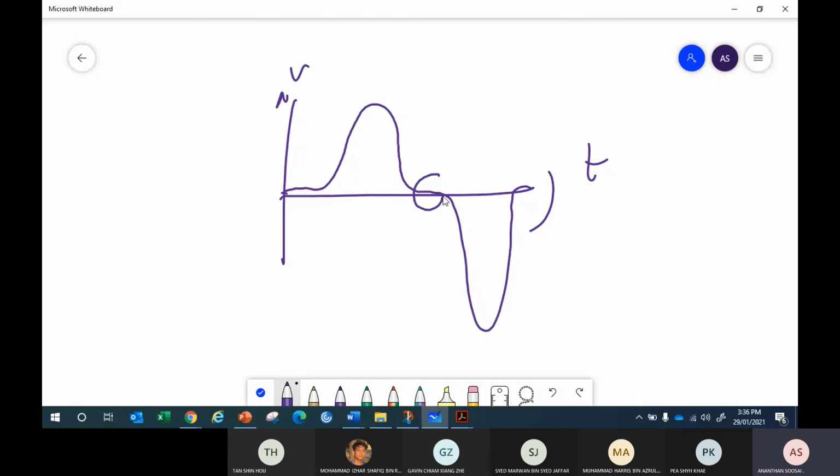So there is a region where voltage is 0. At this condition the magnet is totally inside the coil. No flux change, no EMF. Only when it is approaching, slowly getting into the coil, voltage will be induced. In this region the magnet starts to come out of the coil, then voltage will be induced in the opposite direction.